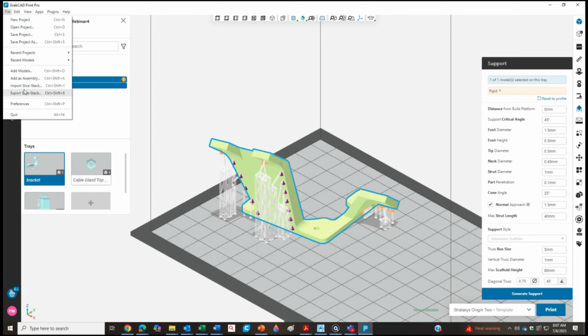Unlike a filament type printer, where each slice involves G-code instructions for the print head movement, with a DLP printer, each slice is a PNG image file. That's what the Origin DLP printer flashes through the glass and the clear tray membrane into the thin layer of resin, curing a single layer at a time to form a complete layer's pattern.